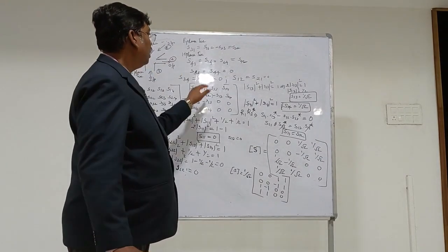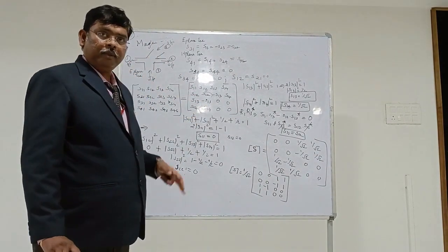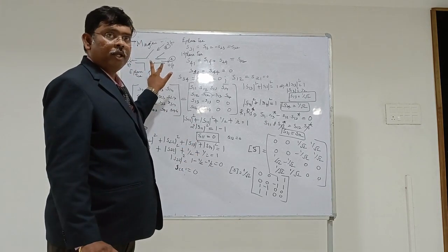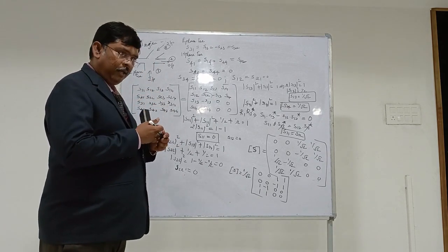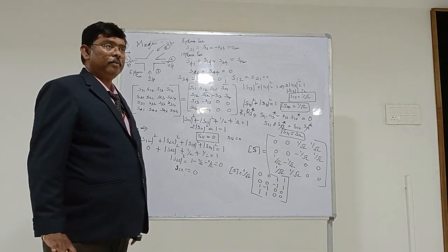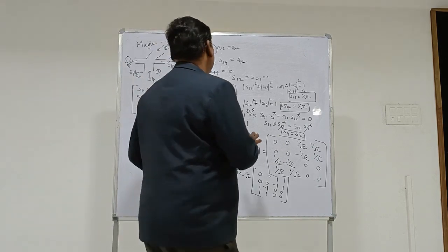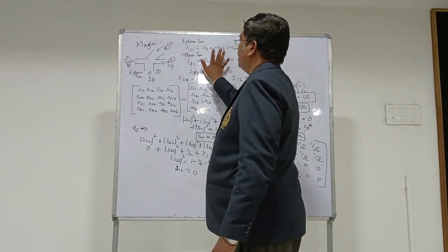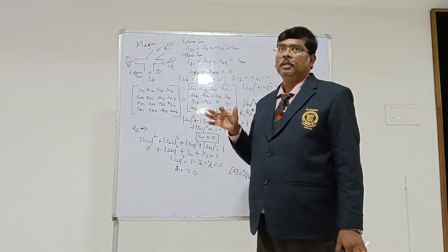Now I conclude how this magic T is working. The magic T is also a 4-port network. These two are the output ports, always 1 and 2. Port 3 is the input port for the E plane, and port 4 is the input port for the H plane. That is the combination of E plane T and H plane T. How we frame these conditions and the symmetry property applicable for this device is most important.